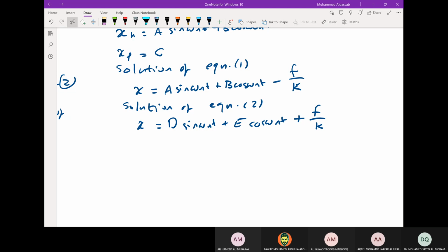Here it is friction damping, or Coulomb damping, and the frequency of oscillation will be omega n, because we look at the argument of sine and cosine in all the solutions. If you proceed to the second cycle, those terms will not change. Sine omega n t and cosine omega n t will again appear, plus a constant.